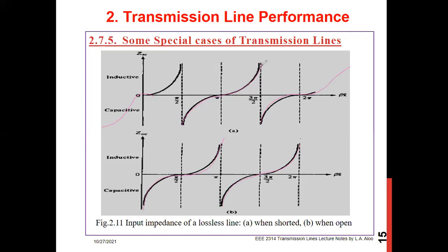Only that when we have the open circuit scenario, it will start by being capacitive, then it goes inductive. Capacitive, then inductive. Here, in the short circuit case, it starts by being inductive, then goes capacitive. Inductive, then capacitive.